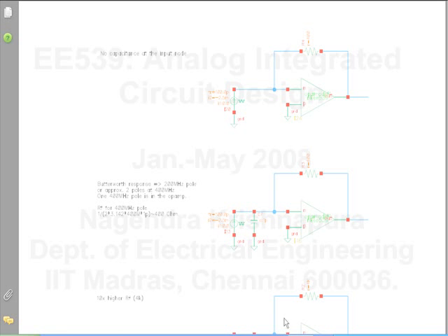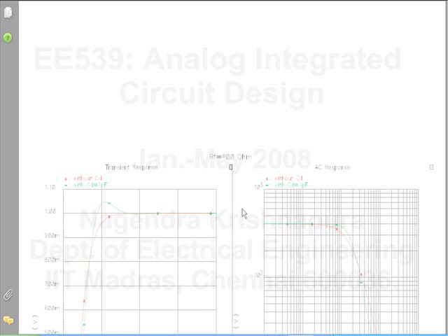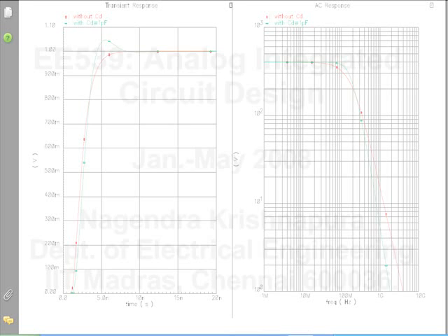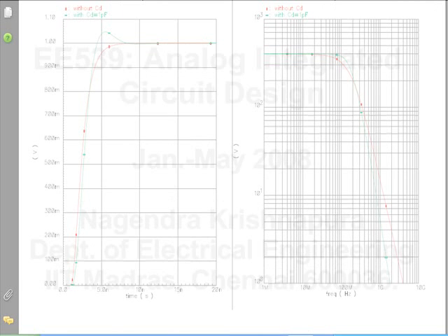So, this is what I also simulated before I set the question. I don't think there is anything complicated with the simulation. Once you have the op-amp model, the whole thing works quite easily. Is this visible? Yeah. So, the red stuff is, if you don't have the diode capacitance, it's a first order system. So, there is no overshoot or anything, and also here you see a first order behavior. I think the lines are rather thin, but I think it's still visible. Now, with the capacitor and the response being adjusted for maximal flatness, you get some ringing in the time domain, not too much, maybe about 5%. And then you see that the bandwidth of the green curve is beyond the bandwidth of the red curve.